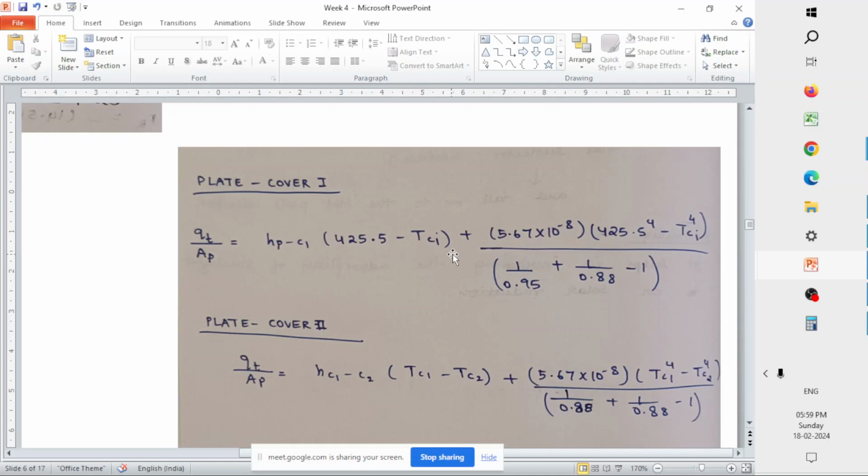So what kind of different materials we can actually explore for the flat plate, for the absorber plate. Like that, you have the transparent glass cover. Can we use some other glass cover or some other material in such a way that we can trap almost all the solar radiation that comes into the system, but not let any of the radiation go back to the atmosphere due to the convection and the radiation losses? Is there any possibility, do we have any material in such a way that we can minimize the convective and the radiation losses to a much greater extent than what is present today?